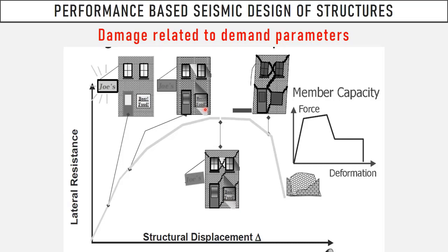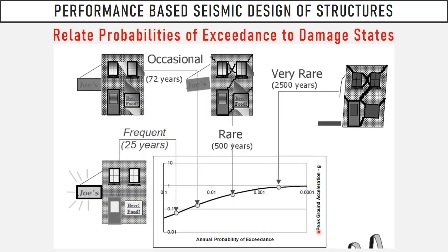But with the introduction of the performance earthquake engineering approach, the design or the check of the performance is related to a demand parameter. This time, this is not force, this is deformation. Or, okay, you define a damage state or a damage parameter, but what is its probability? You should also define its probability of exceedance of a damage state.